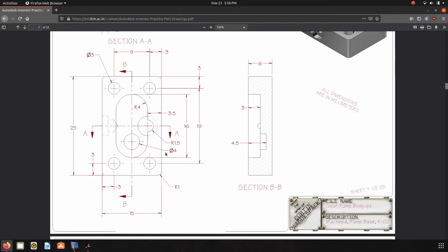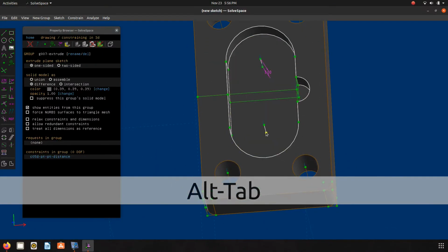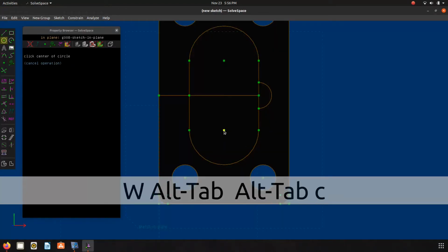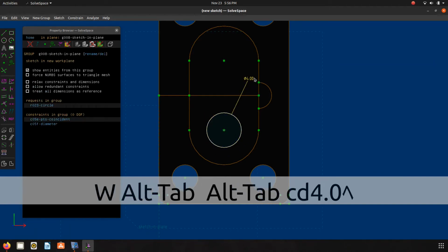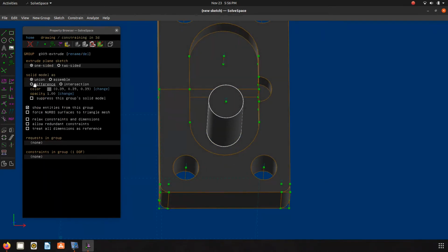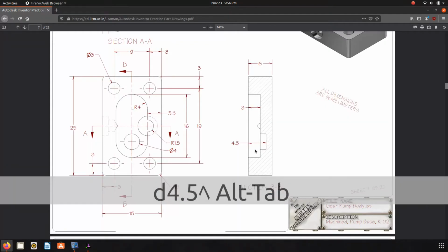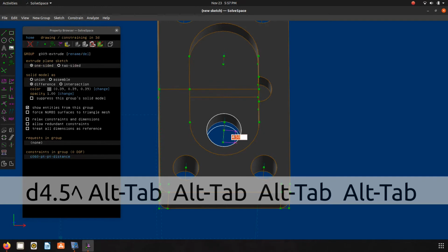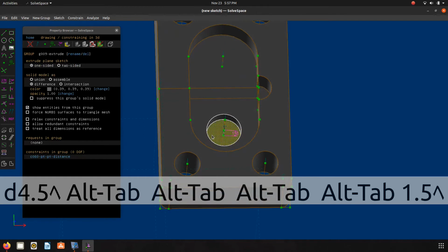Okay, and then let's see here. Let's put in this 4 millimeter point there. You can just select that and hit Shift W, and it's right on that. See the diameter of 4.0. Okay, and that's 0 degrees of freedom. We'll extrude that. That's going to be a difference. 4.5 millimeter. Nope, 4.5 from the top, so it's really only down 1.5. Okay.